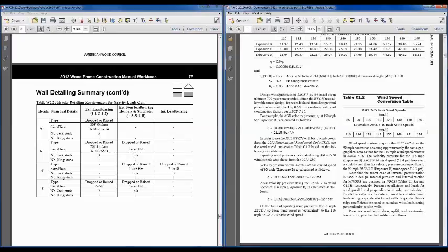I'll take that question though, Michelle, and we'll say that we are creating some additional guides above 160 miles per hour. I think we're going to do up to 170, maybe 180. You can see in our tables we go up as high as 195 in the wood frame construction manual, which is equivalent to the old 150. And so we're going to tabulate 170 and 180 high wind guides for exposure C. Our understanding is exposure C is required once you get up to those higher wind speeds. Okay. And looks like there's some commentary on that too.